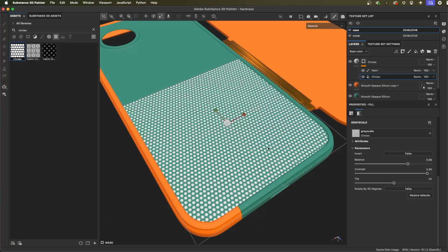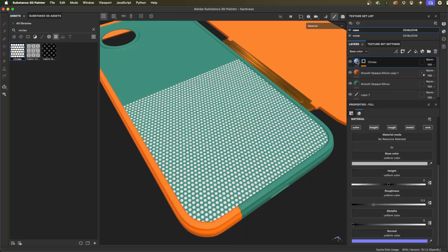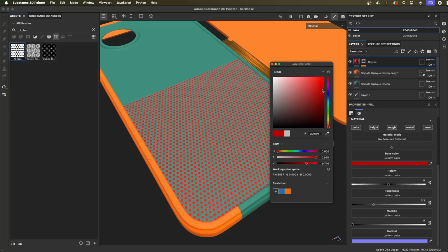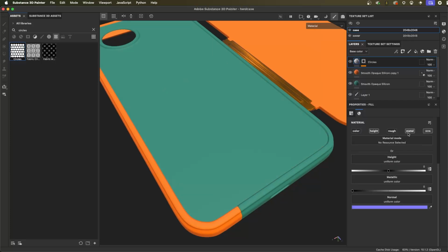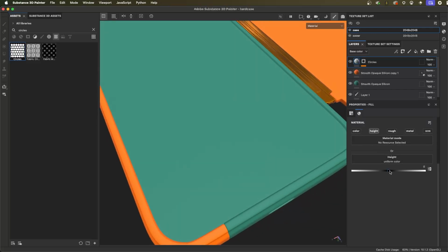Now, the last part of this is going to be pretty simple. We want to make some adjustments to the material channels themselves. So what I'll do now is come over here to the material. I click on the material swatch. You can see I'm on the material tab, and we have all these channels, and I could color these if I wanted to. Like if I wanted these to be red, we could do all that kind of stuff, but I definitely don't. In this case, I just want a little bit of a bump look to this. So what I can do is disable channels, like for example my color, my roughness, my metal, and this normal. We're going to take all that off, and instead, what I'm going to have is just this height information. Now, we can't see anything, so it's at 0, but watch this.